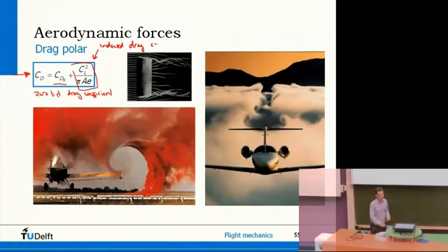So there are some additional parameters, but you can see it's a function of CL squared and some other ones, pi, A, and E. Now pi, of course you know. A is basically the aspect ratio of the wing.